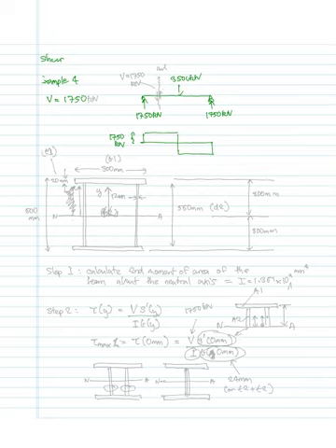So if we had done a cut in the beam at any position, there would have been equal and opposite shear forces. Obviously they would need to cancel each other out just by making an arbitrary cut, and the value of the shear force is 1750 kilonewtons. So that would be the shear force that needs to be designed for if that had been caused by a 3500 kilonewton force in the center of a simply supported beam.